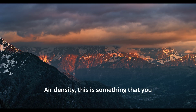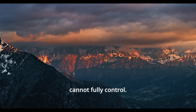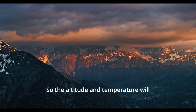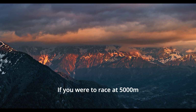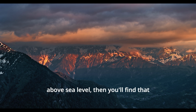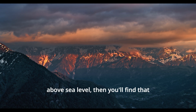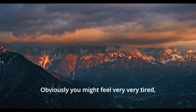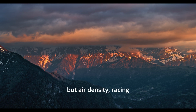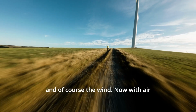Air density: this is something that you cannot fully control, so the altitude and temperature will affect how dense the air is. If you were to race at 5,000 meters above sea level, then you'll find that for the same power you'll be able to go very, very fast. Obviously you might feel very, very tired, but air density, racing conditions will affect CDA, and of course the wind.